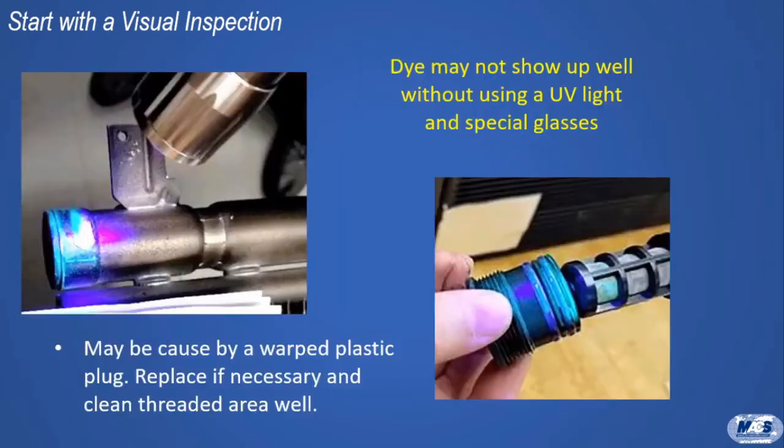Dye will appear more prominently on high mileage vehicles and on systems with more severe leaks. However, signs of dye might be harder to see on lower mileage vehicles. Dye should not be found at the blind coupler or tube connections with this condition.